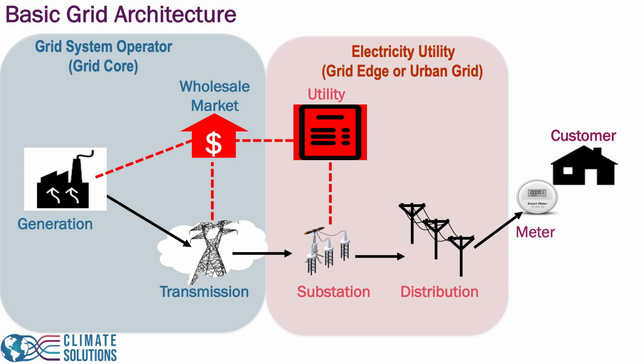A grid system operator dispatches generators, meaning it decides which generators will run, to match the power demanded by the utilities at a minimum total cost in a way that it satisfies the power transmission network constraints. Since there is no electric storage, at all times we have to ensure that generation meets demand.